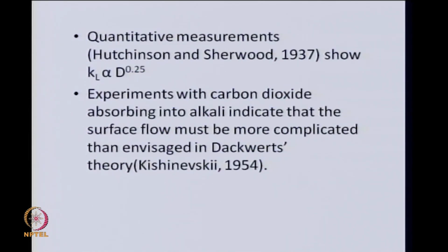And experimental measurements by Sherwood's group reveal scale proportionality to diffusivity to about 0.25, again at variance with the expectation from surface renewal or penetration models. That goes on to support what Kishinevsky has been advancing, that in experiments like carbon dioxide absorption into alkali, the surface flow is probably much more complicated than has been envisaged in the Danckwerts theory.